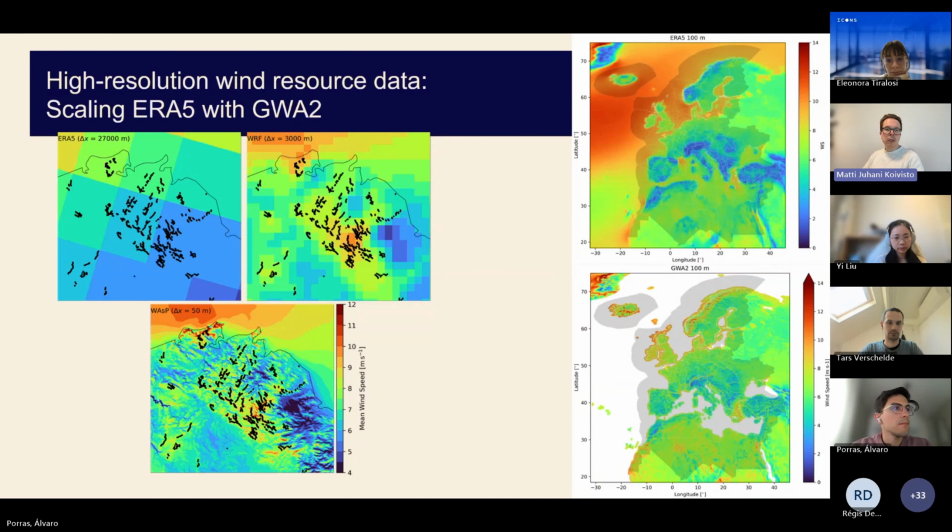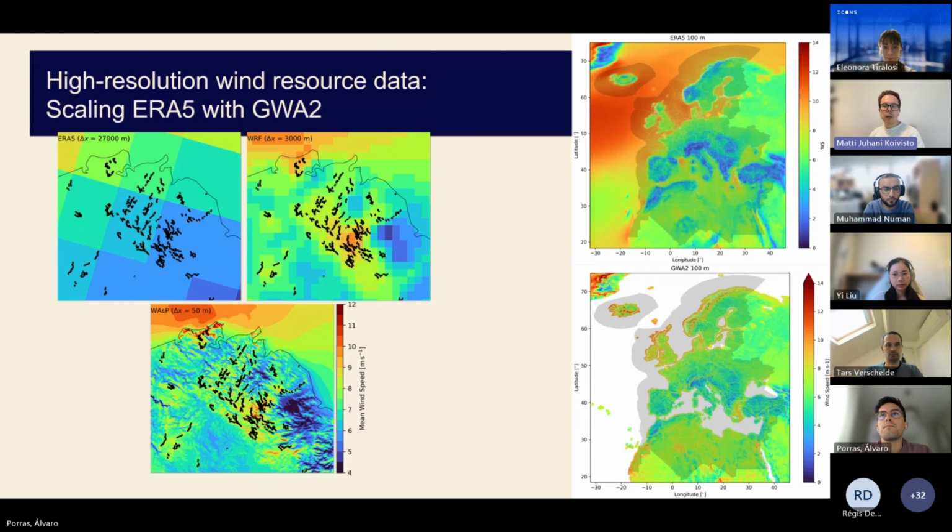Whereas in the bottom left, you can see when we pull it to the global wind resolution, there's a lot of high resolution that brings out when we do that. And of course, in this example, you can see the turbines are placed actually in the higher wind locations, as you can imagine that the developers would like to use the higher wind locations. So if you stick to ERA5, you simply don't have the resolution to capture this kind of more local winds.